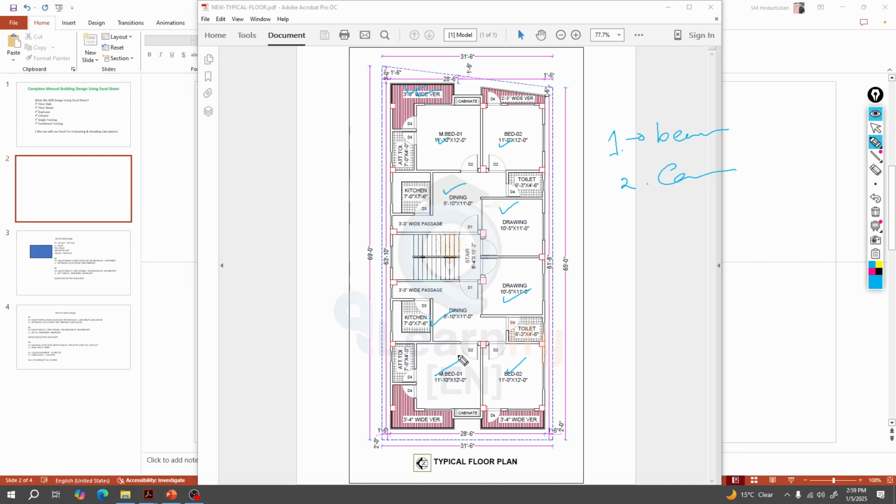Because if you provide a different slab thickness and reinforcement specific for slab 1, and for slab 2, slab 3, slab 4, then it will not be a good practice, because when our workers start working, they will face great difficulties. So for that type of simple structure, we'll consider the same thickness and then we'll use the same reinforcement spacing.